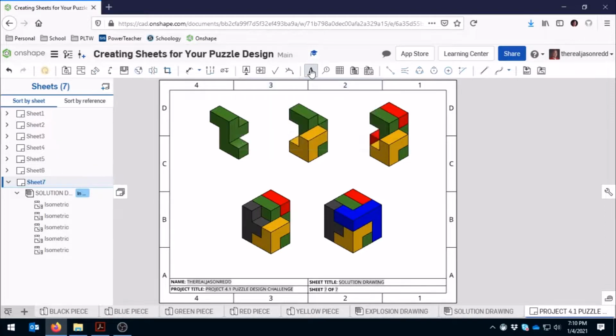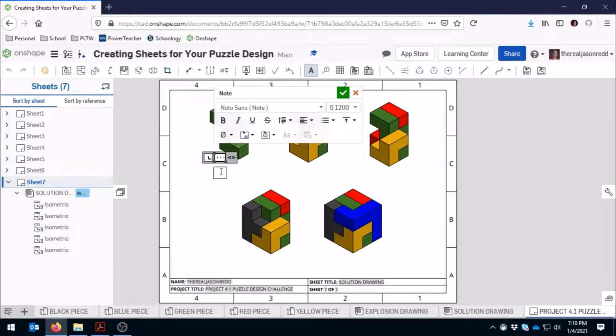So we're going to choose text, and just somewhere below step 1, you're going to see this come up, and you'll notice that this allows you to expand it. So I would go ahead and expand that a little bit. We're going to change our font size to 0.25, and when you choose a drop down, you may not see another size there, but you can change this. So we're going to change this to 0.25, and then I'm going to come back into here, and again, it didn't take the size of my font, so I had to hit enter to accept that.